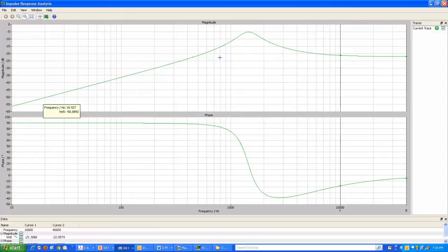output impedance, or V tilde over I tilde transfer function, and for this particular system it is always less than 0 dB, so it does not amplify the load current perturbation, and it has reasonably low gain values at low frequencies, but becomes higher as you go to higher frequencies.